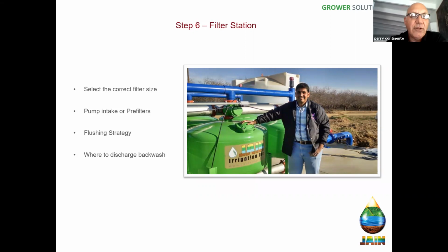Okay. Some of the other things that we do is we want to make sure that we have the correct filter size. Like, how many filters should we have? It depends on the water quality and how many gallons a minute we're going to put through each filter, given the water quality issues.